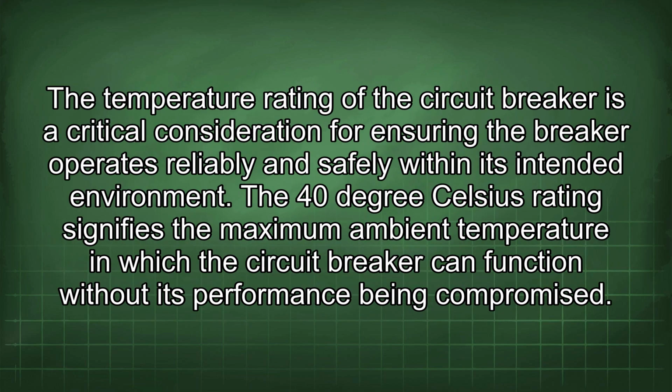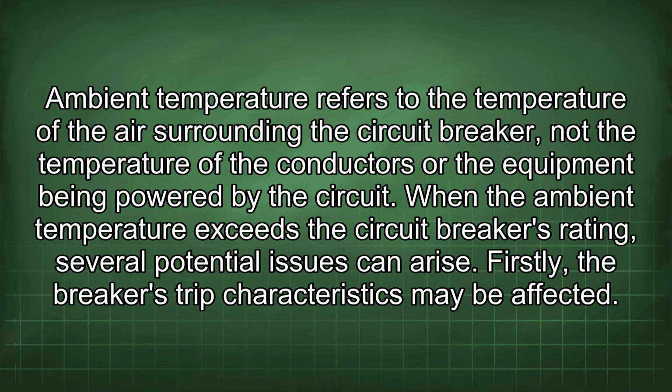The temperature rating of the circuit breaker is a critical consideration for ensuring the breaker operates reliably and safely within its intended environment. The 40°C rating signifies the maximum ambient temperature in which the circuit breaker can function without its performance being compromised. Ambient temperature refers to the temperature of the air surrounding the circuit breaker, not the temperature of the conductors or the equipment being powered by the circuit.